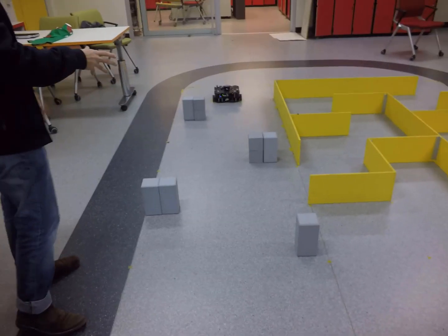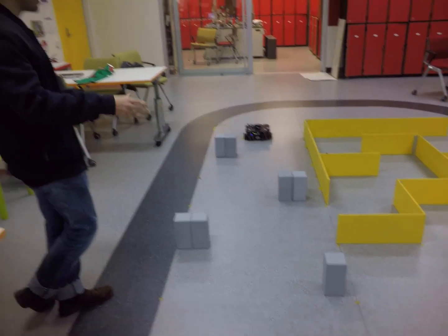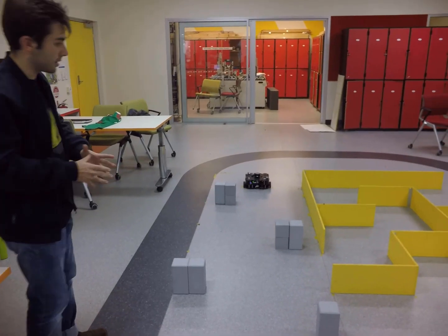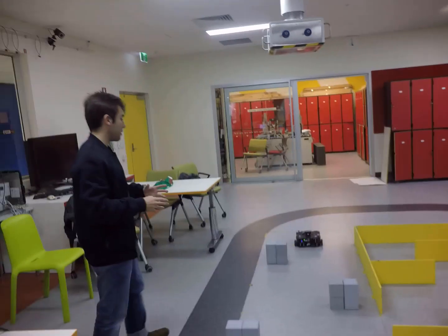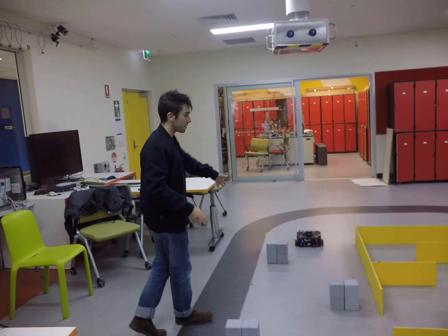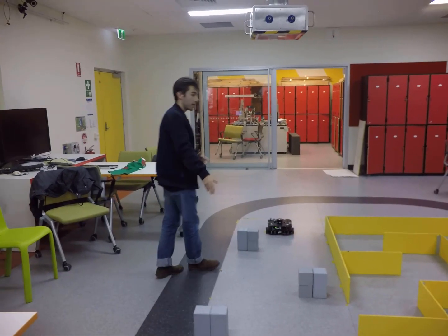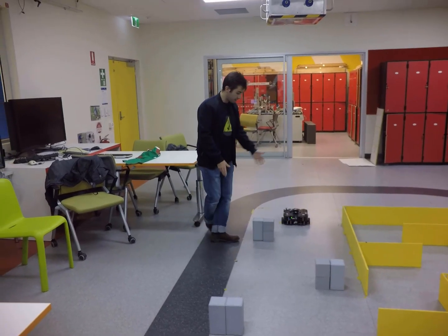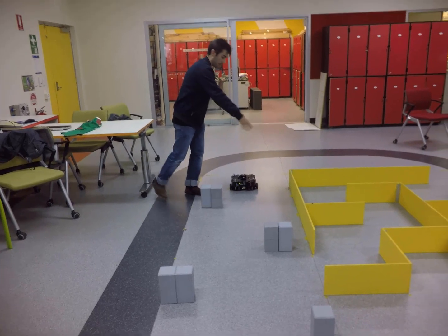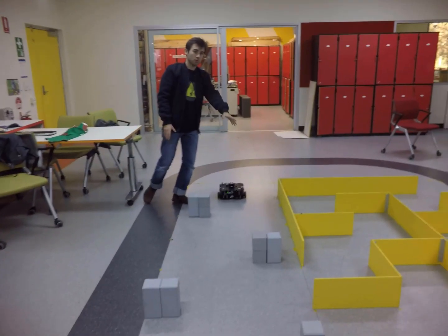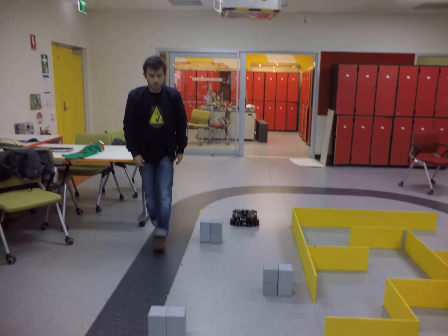Each of the LiDAR scans is taken in and turned into a histogram, and it determines which spaces are free and which spaces are not free. So if you look at this and say, oh, there's an obstacle here, don't go that way, there's a space out here, so steer more towards that direction.